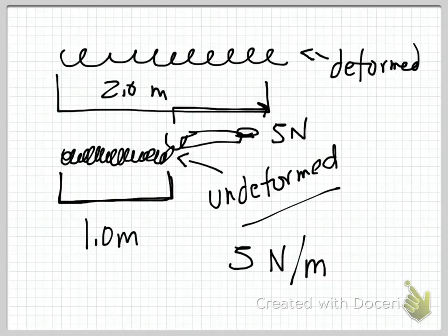If you're designing a system, you would be looking at how much tension you need on a part, like I said, especially mechanical. You would specify the spring constants for the springs you needed. And you might have a manufacturer who you say, well, look, we need springs that are 20 centimeters long that have spring constants of 135 newtons per meter.